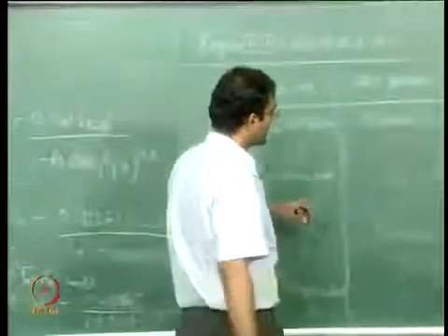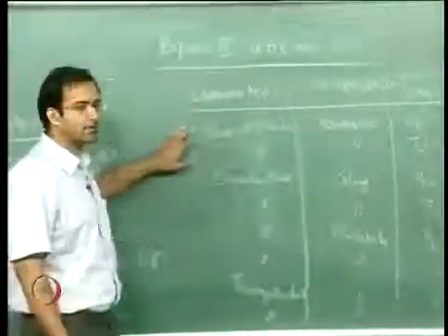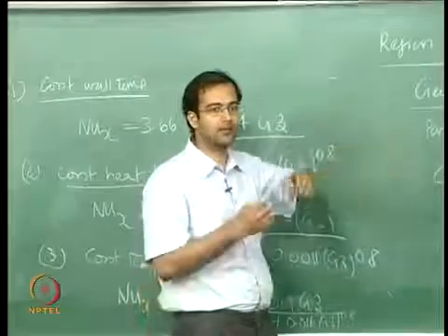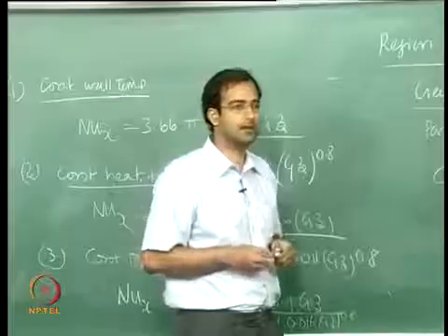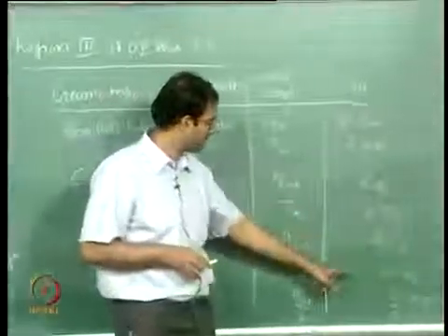Then you can see the order in which the Nusselt number decreases. So it is the highest for the parallel plate case, and compared to the constant wall temperature, constant wall flux has always a higher value of Nusselt number. Then comes your circular cross section, okay.